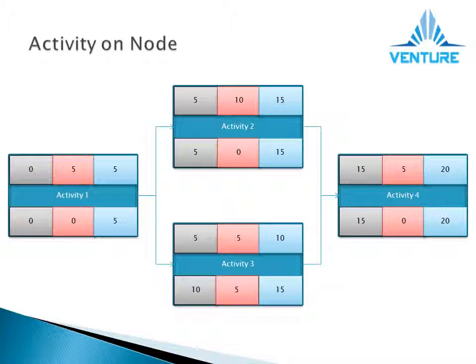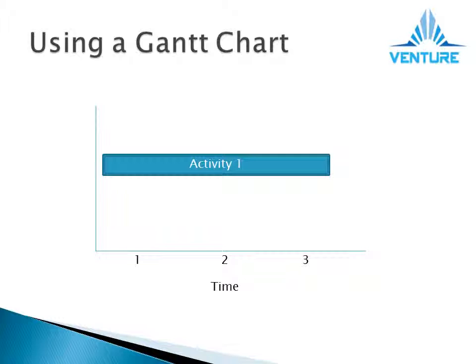As previously mentioned, this method allows the critical path to be calculated. This is the most important path, where there is no flexibility regarding start times and duration of the activities. Should the activity take longer than anticipated, the whole project will be delayed. In this example, the top line is the critical path as the float of all nodes is 0. So just to recap, this was calculated by doing the latest start time minus the earliest start time. Remember, we work backwards to calculate the bottom line of each node.